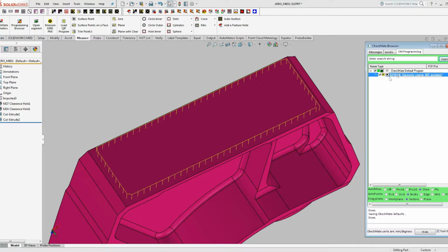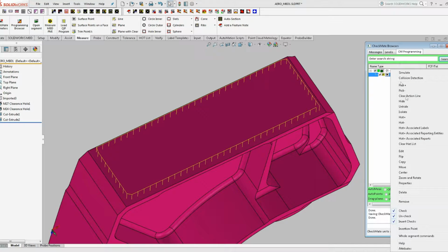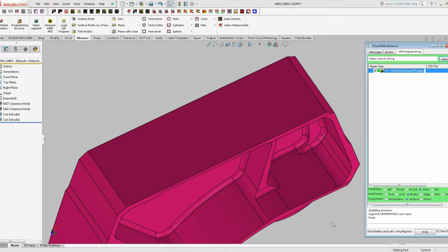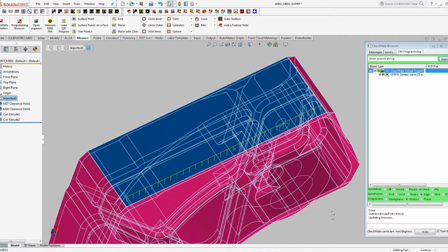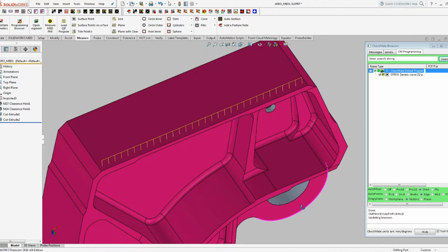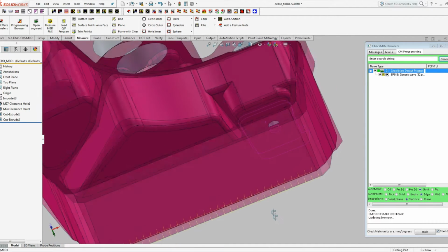I'm just going to delete this set of measurements that we just created. And I'm going to go over here and click on Edge on the auto points. And edge is very similar because all it does is it puts a row of surface measurements along the edge of a face that you click. So whatever edge you click closest to, it's going to put some measurements along that edge. Sounds simple, but there's a lot of other neat options that you can use with that edge modifier.